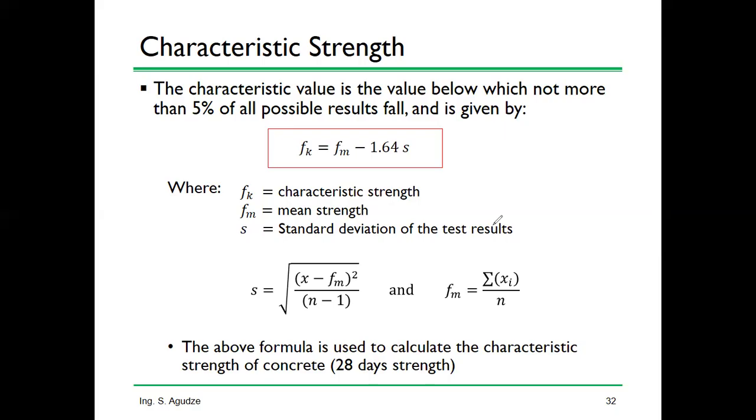Okay, what they are doing is correct. We first of all do mix design and then decide on our ratio before the work starts. While the work is ongoing, we do what we call a confirmatory test to confirm that what we are expecting is what we are getting.